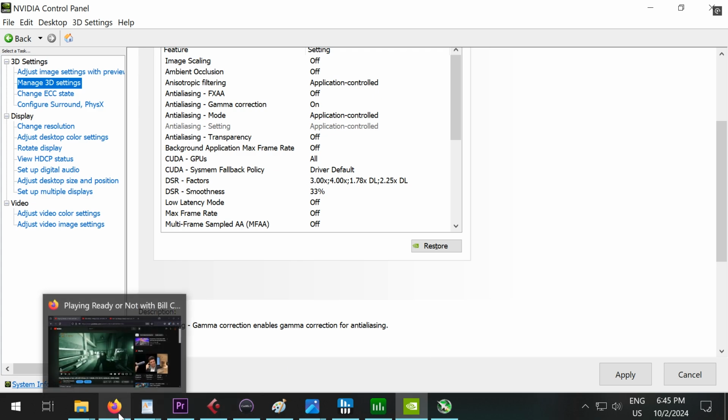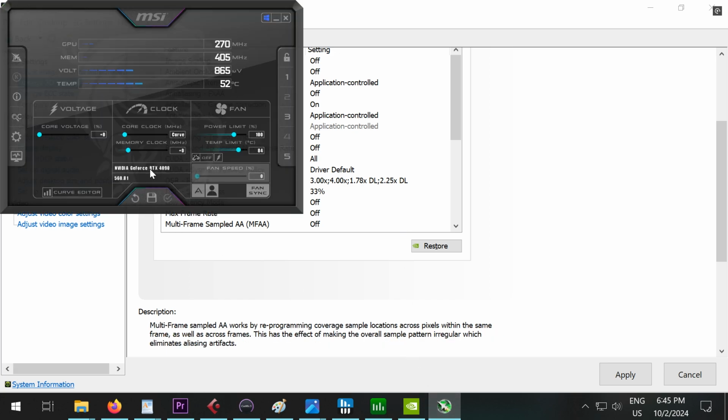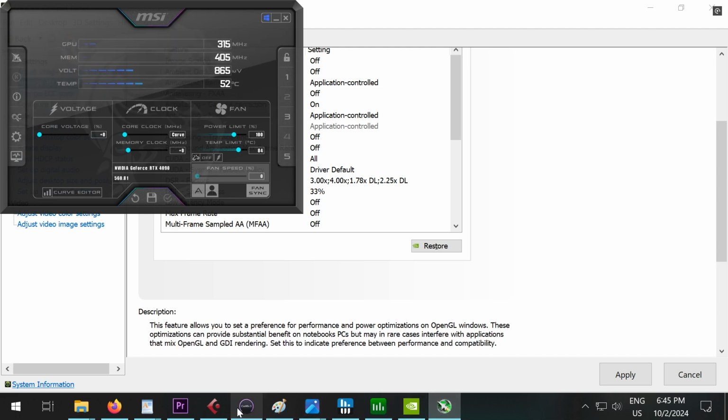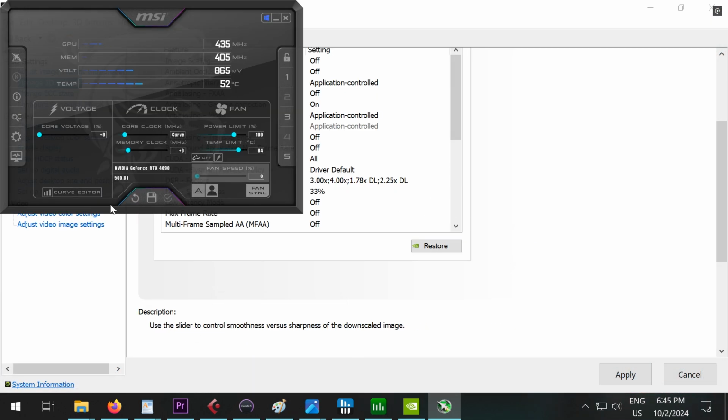You're feeding too much power through that rail, and then the weakest point is within the GPU, because all the current, all the heat, and all the electricity is being condensed on that one 12-pin high-powered cable, and then it just melts. So in my case, I did 3 cables just in case, because I don't need that much wattage, and then I stepped it down with an undervolt, but quote-unquote overclock. So I'm going from 2805 megahertz to 2820 maximum.